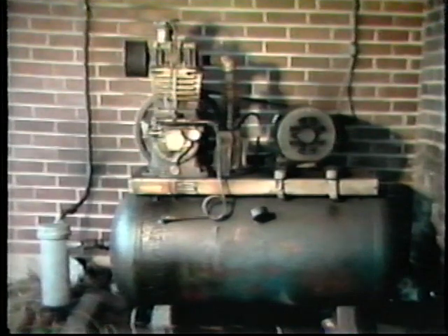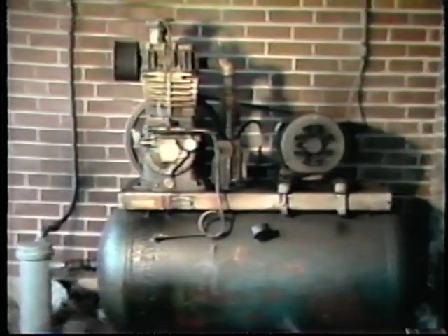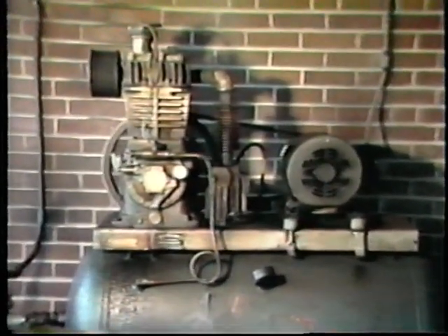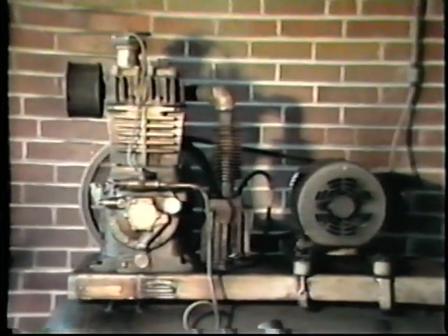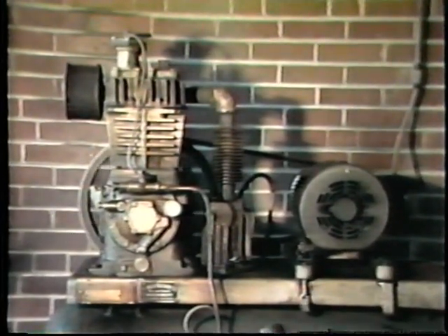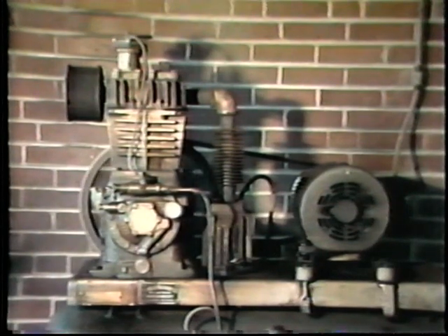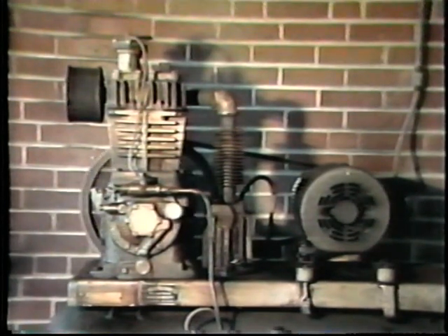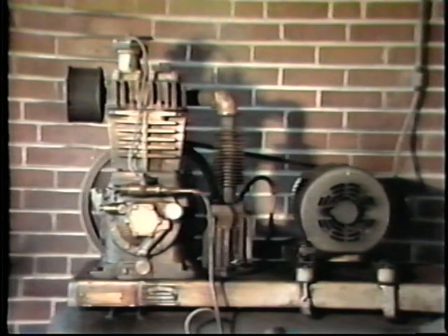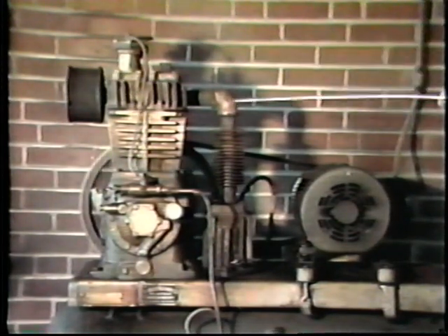First, the most common type of positive displacement compressor found in industry today is the reciprocating piston compressor. The one you see here is a small two-stage compressor that's seen a lot of good use. Driven at rated speed, this unit will take 20 SCFM and raise it to a pressure of 100 psig. The motor is connected by belt to the crankshaft here. And here are the inlet and output ports.